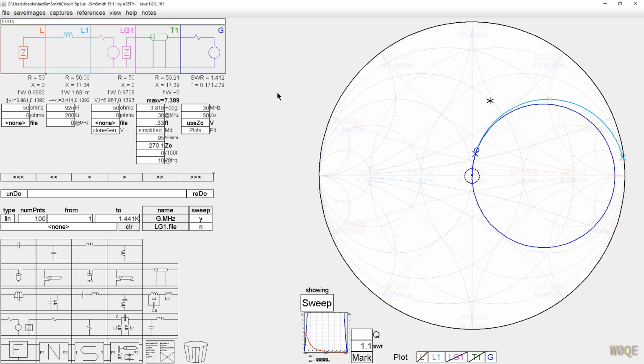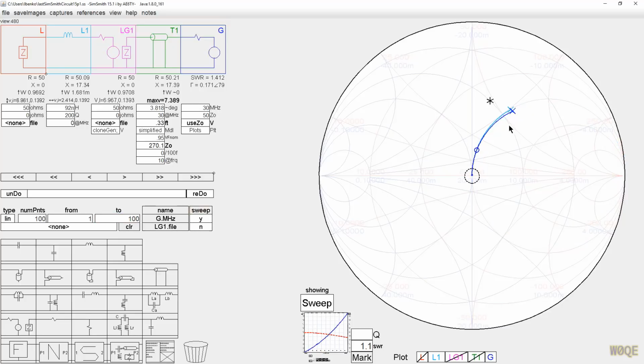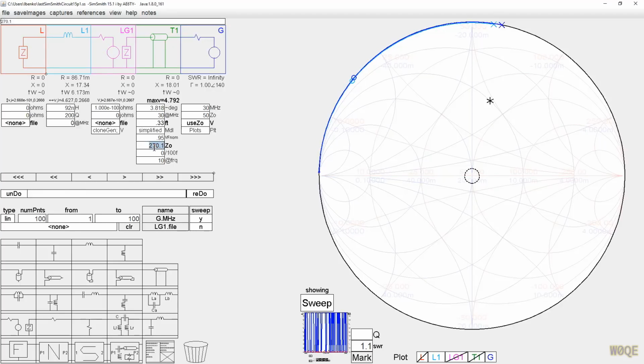But anyways, these are small details, and either one of these two circuits over the range up to 100 megahertz were incredibly close, considering that the outcome is matching these two types of impedances. Now this was against 50 ohms here. I could do this again against 0 ohms, and we'd see that maybe I didn't quite get the right impedance then. Okay, it's a 260 ohm piece of transmission line, but we can see that both of these are a heck of a lot better than doing nothing.